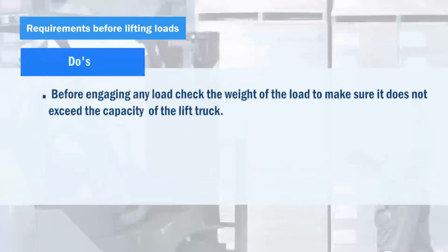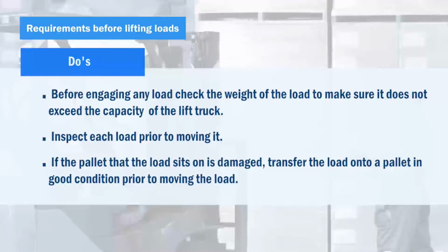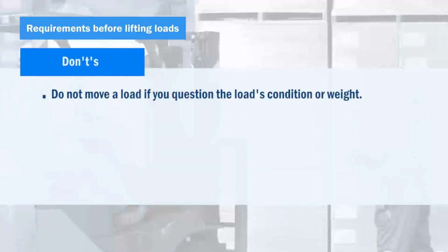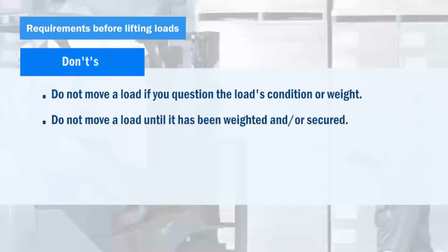Before engaging any load, check the weight of the load to make sure it does not exceed the capacity of the lift truck. Inspect each load prior to moving it. If the pallet that the load sits on is damaged, transfer the load onto a pallet in good condition prior to moving the load. Do not move a load if you question the load's condition or weight. Do not move a load until it has been weighed and or secured.